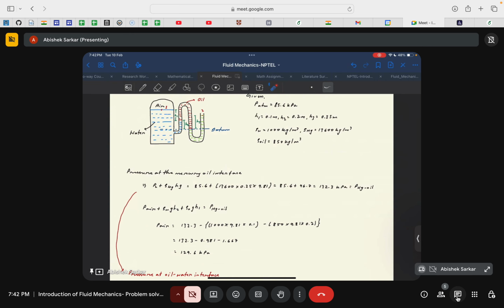There was another way that was pointed out, and I think there's a much easier way. If there are several layers of liquid in this kind of series of U-tube manometers, you just consider the concept of going up and down the manometer. From a particular reference point, if you are going down to measure the pressure, then the pressure will increase, and if you are going up, then the pressure will decrease. That's the basic concept. In this kind of scenario, the problem of the interface being at the same liquid is not there. So you just need to go up and down and find the pressure.